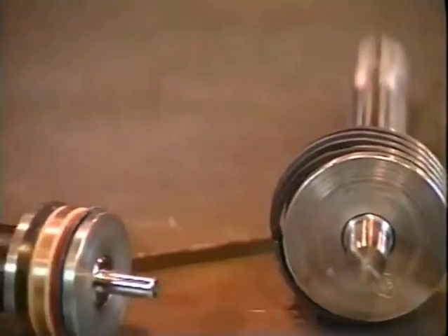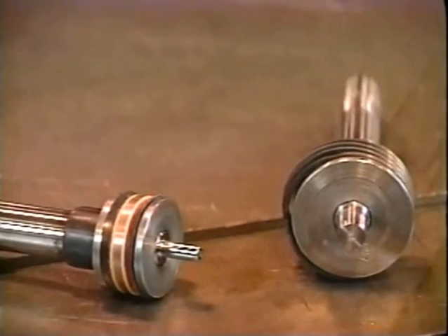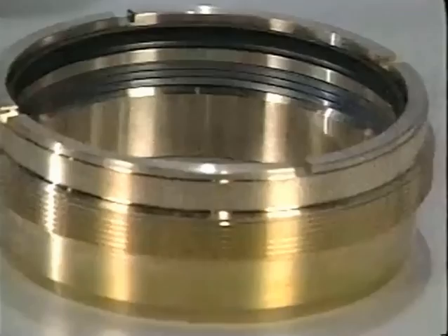This is done with cast iron piston rings or with seals made of a flexible material. Cast iron rings last longer but may allow unwanted leakage. Flexible seals may not last as long as cast iron but do form a positive seal.